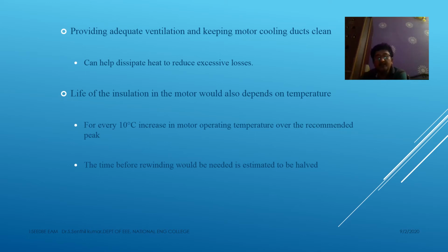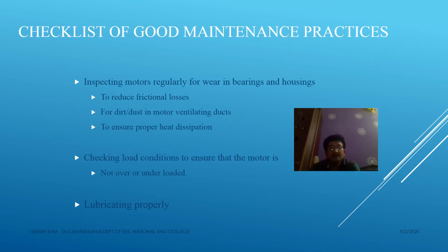For every 10 degrees Celsius increase in motor operating temperature over the recommended value, the time before rewinding is needed is estimated to be halved. And there is a checklist for good maintenance practice that we have to follow.